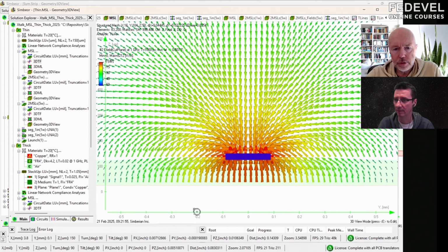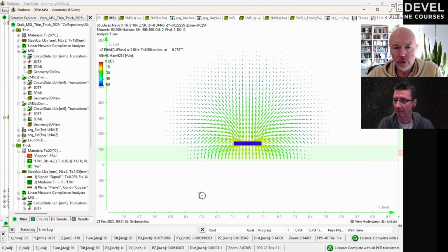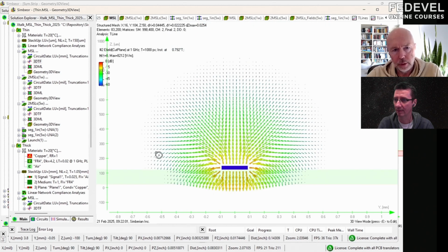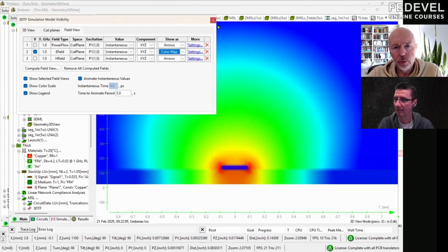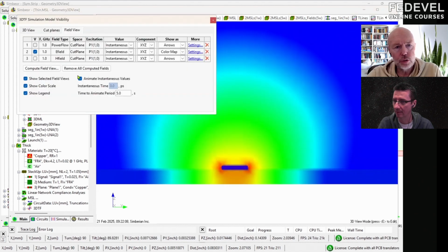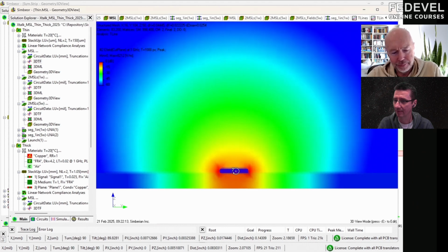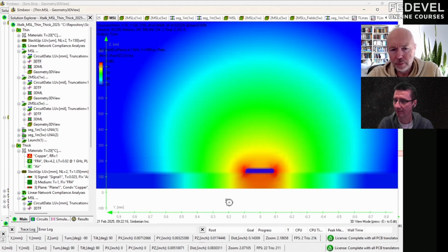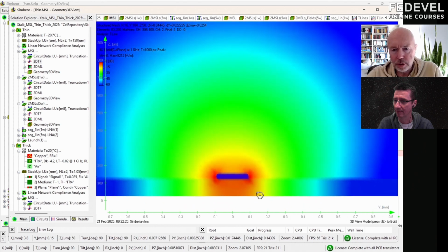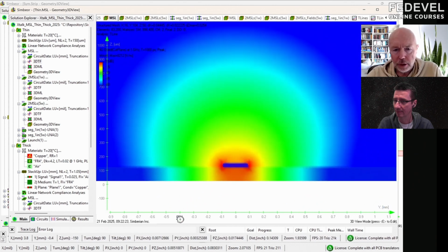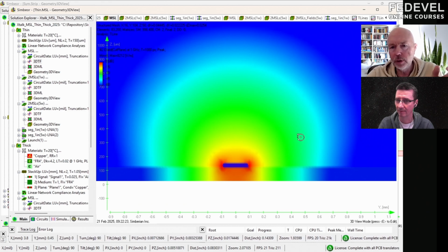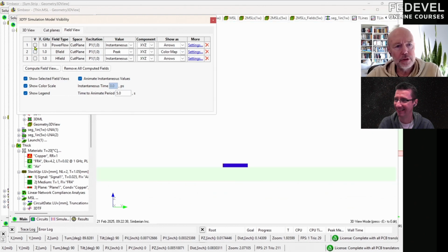And you can see that on this scale here, and let's just make a comparison with color view. And just to stabilize it a little, we can take a look at peak value. So again, I switch to side view and I use just the S button here. And you can see that right here, the spread is from minus 0.6 millimeter to 0.6 millimeter. So it's essentially a 1.2 millimeter spread of the electric field. It's pretty much the same as the power flow.